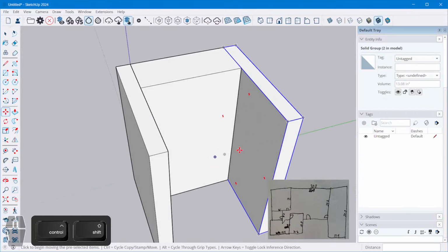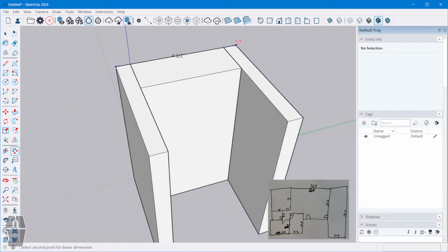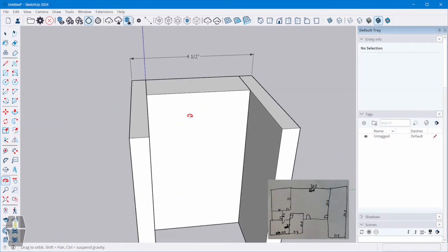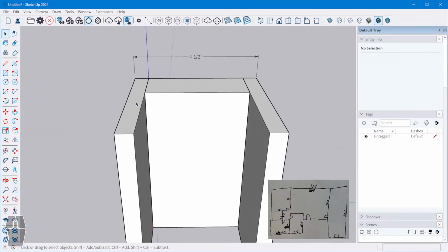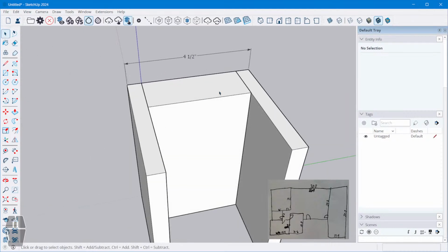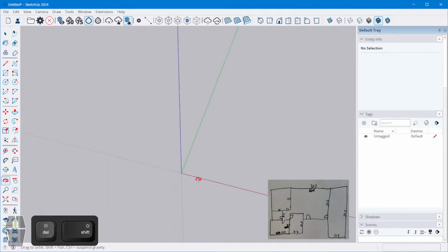Now in garages, you'll either have 2 of these or you'll have a 5/8 thick drywall. But our wall thickness here is if we have a 2x4 with 1/2 inch drywall on both sides, you're going to end up with a wall thickness of 4.5 inches. Now, again, this is assuming we're using standard drywall, standard studs, that kind of thing. If you're working on a trailer house or anything like that, your mileage may vary, but that's what we're going to be working with.